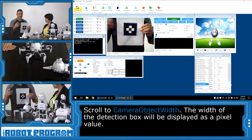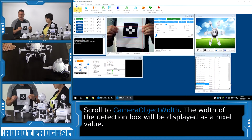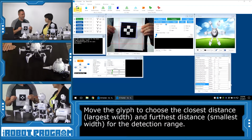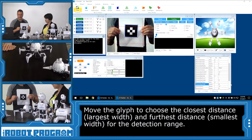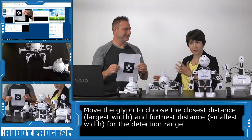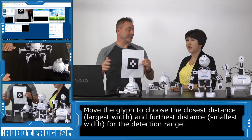So whenever we do this application, this practice, you're going to want to make sure the square is the same. So I think the numbers that I'm going to go with is anything greater than 110, the robot is going to move back. And anything less than 90, the robot's going to come forward. So you're giving it about a 20 range there. Yes. So it's going to try to go forward or back, depending on how far or close the glyph is. So if it's in between that range, it's just going to stop. It's not going to do anything at all.